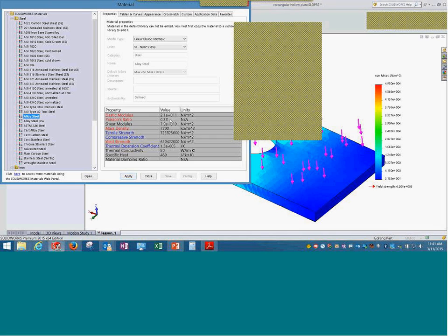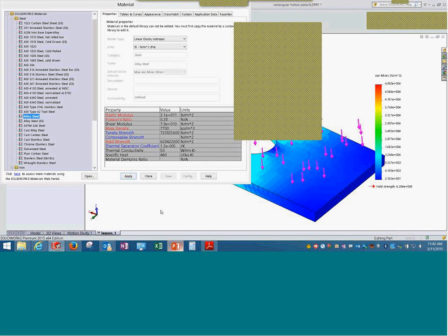first we need to understand what Poisson's ratio is. Poisson's ratio is the ratio of lateral strain divided by the strain that is happening in the axial direction. So if it is 0.5, which is an absolute condition, and I press the part in a certain direction, all the volume will automatically move in the other two directions.